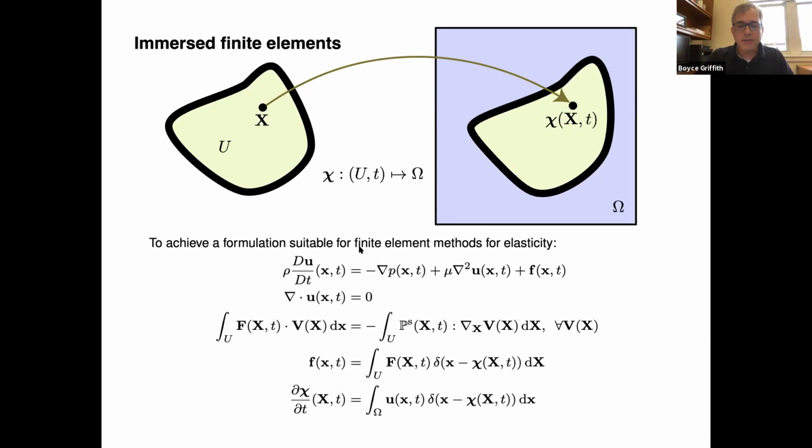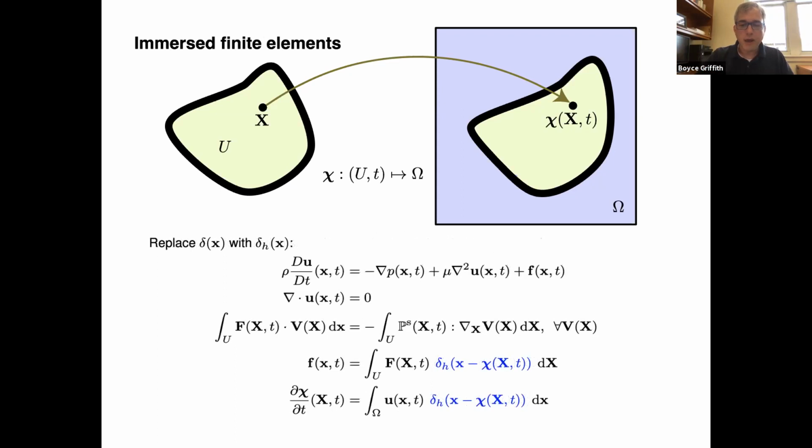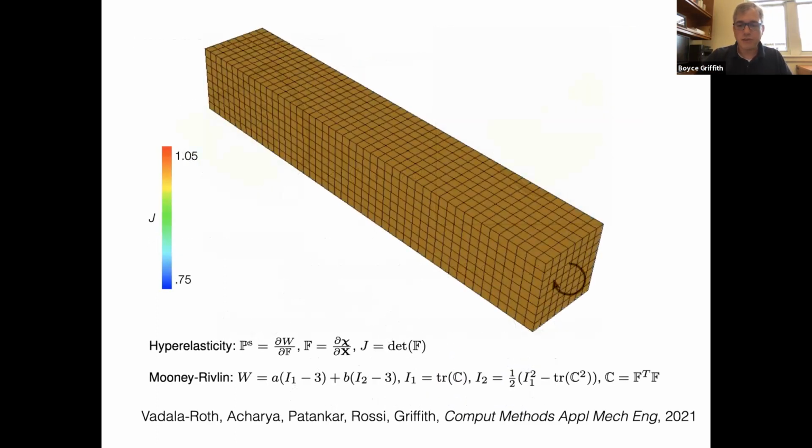To do that, you can get an equivalent body force by integrating by parts. If you do this the right way, the transmission force term winds up vanishing, and you're back to a method that is very similar to the classical immersed boundary idea that I introduced a few slides ago. And then, of course, finally, we're going to replace the singular delta functions with regularized versions of the delta functions.